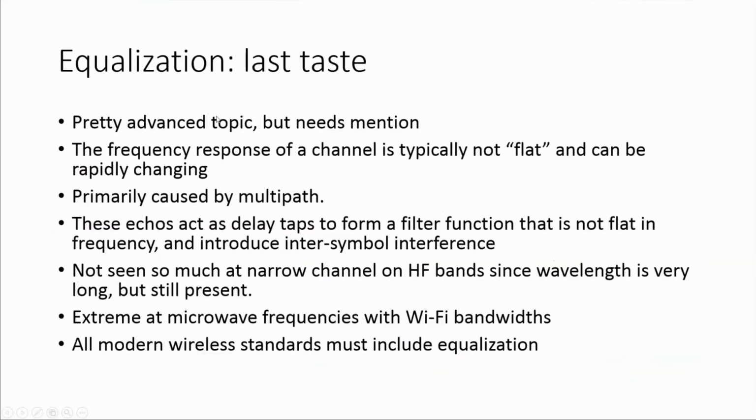Okay, so very last slide. Oh my gosh, 9:10. I mentioned equalization a bunch of times. This is an advanced topic, but it definitely needs to be mentioned. What we assume in the channel capacity is that the channel is flat in frequency. The noise is flat and the frequency response is flat, and it's not changing. But that is completely bogus. No channel for any modern wireless communication scheme looks like that.